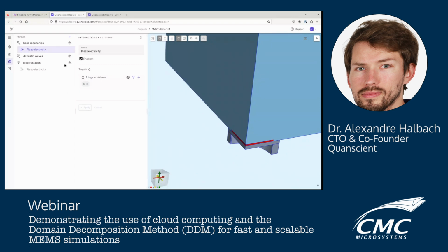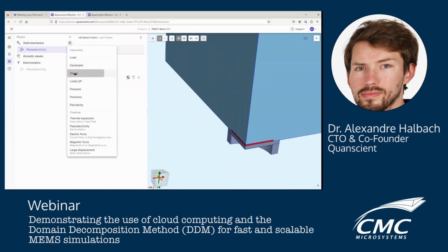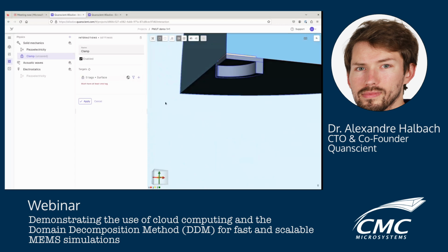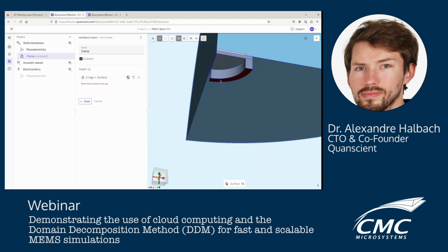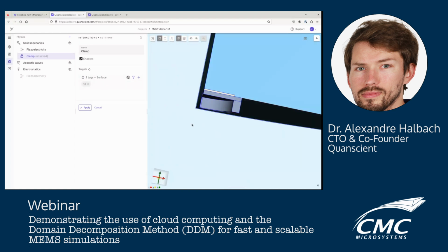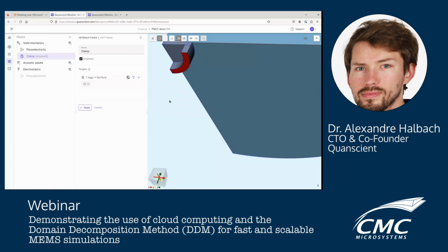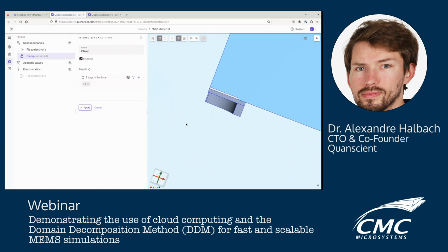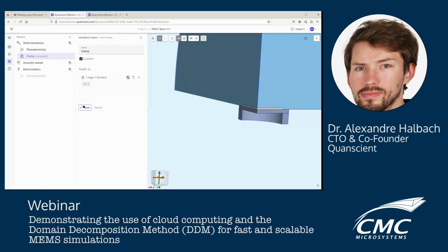And then we want to set up also some clamping boundary conditions. So several ways to do this here. Different clampings give you slightly different results. You could just clamp the whole surface everywhere around it. I could also just clamp the bottom. This would kind of mean that it's edged all around, which is not the most physical, but I could just clamp this as well. Doesn't matter that much in this demo.